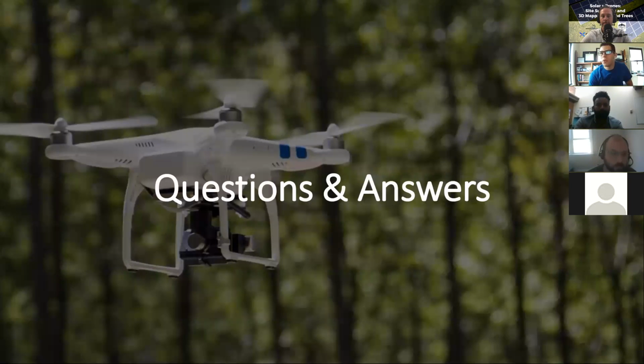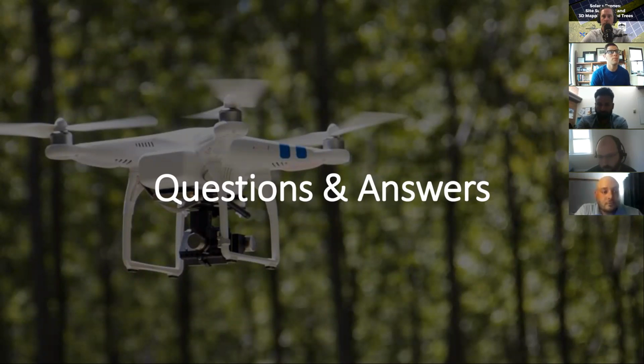One of our first questions is specifically, can you work off of a hotspot when updating a drone? So I'm going to turn it over to Keith to start. Hi, everyone. Yeah, so the short answer is yes, but typically updating the firmware takes a lot of bandwidth. So if you have good service, then yes, but typically I don't recommend doing that. Try to do it at home beforehand. Check the morning of or the night before.